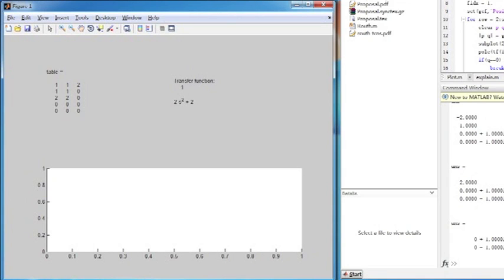But if we have a row of zeros before we get to the end, as seen here, then our polynomial has only even exponents of s, indicating the roots are on the j omega axis. In this case, we know that the system is marginally stable. And this is how Routh-Hurwitz table